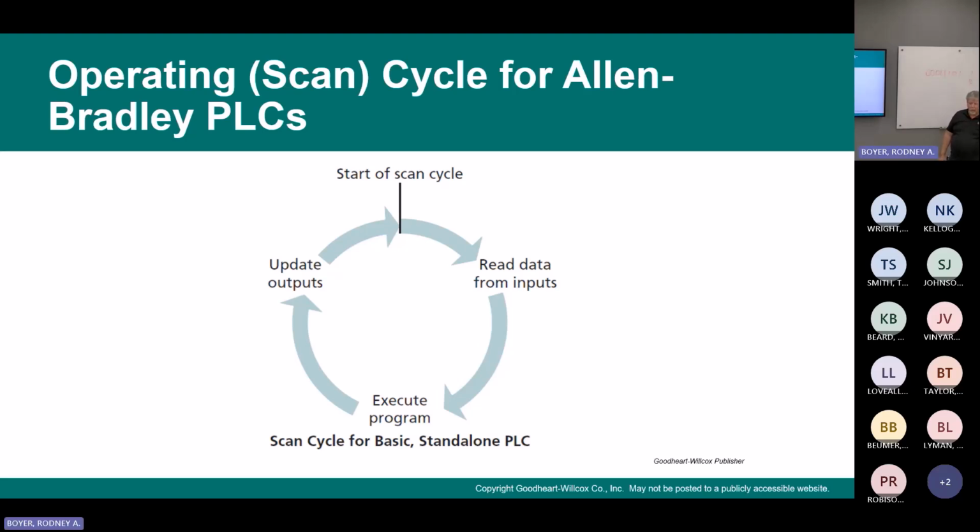Then it executes the program, your user program. It processes the logic from top to bottom, left to right. It cannot and will not ever go backwards.